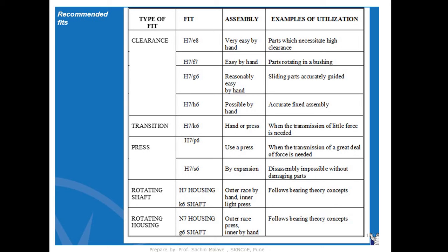But after some time, when the metal cools, or when the component with that hole cools, it will shrink again and its size will come back to its original position. So this is a practical way to carry out the assembly. Here, disassembly is impossible without damaging parts. If you want to dismantle these two parts, the shaft and hole, it is not possible to do easily, and not without damaging the parts.